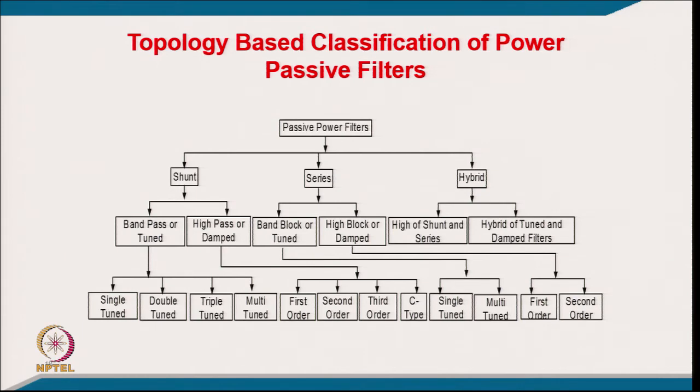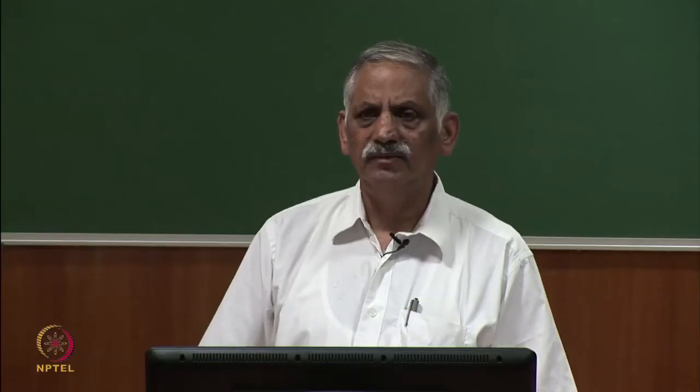Voltage fed load: I have already explained that if you have a diode rectifier followed by a capacitor, which is the majority of loads of such nature, it derives a constant voltage source, because that constant DC voltage source you can feed for the remaining part of the process, maybe LED lighting, maybe your brushless DC fan, maybe your air conditioning system, or washing machine. So, most of the appliances and many such loads, even adjustable speed drives, are voltage source inverter fed, typically an induction motor drive.